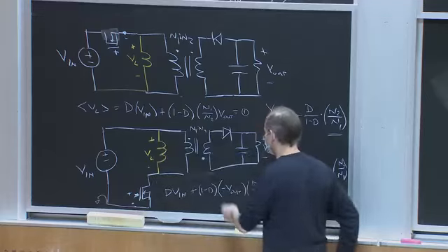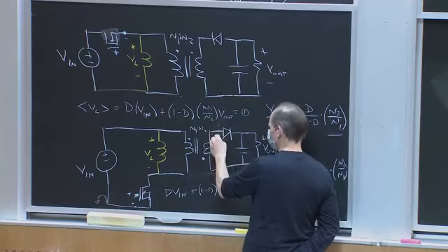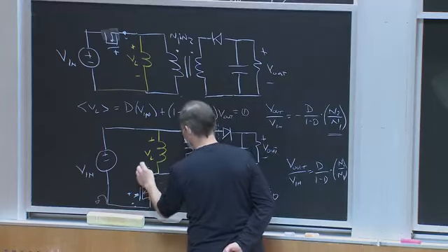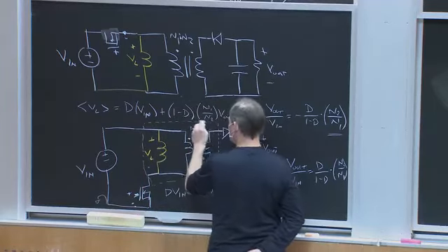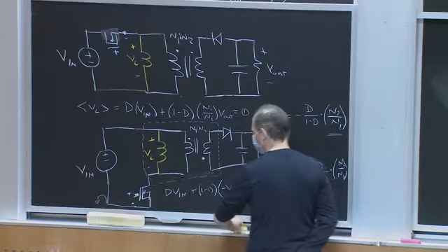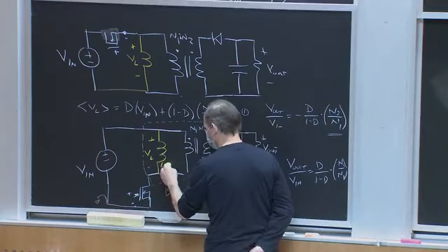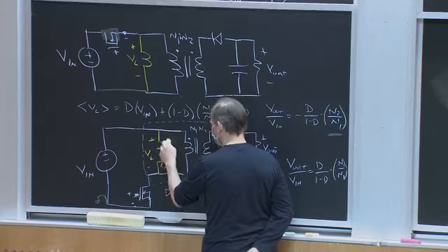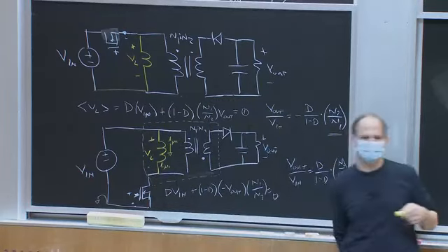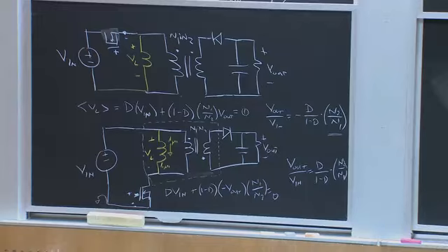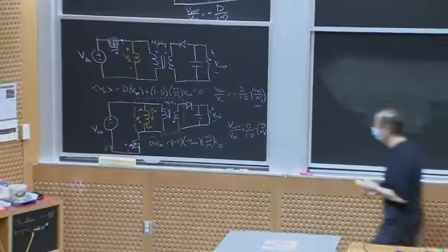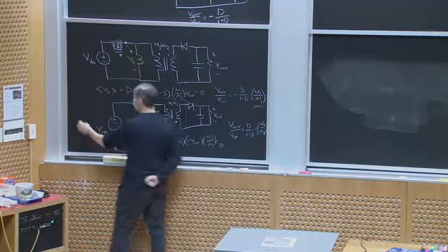Well, what says that I can't just then take this whole thing, okay, and build the transformer just like this. Here's my transformer, and then this L becomes L mu 1, and this becomes I mu 1, and I use my magnetizing inductance of my transformer as my energy storage element. Okay? Done this way, this is often called a flyback converter.